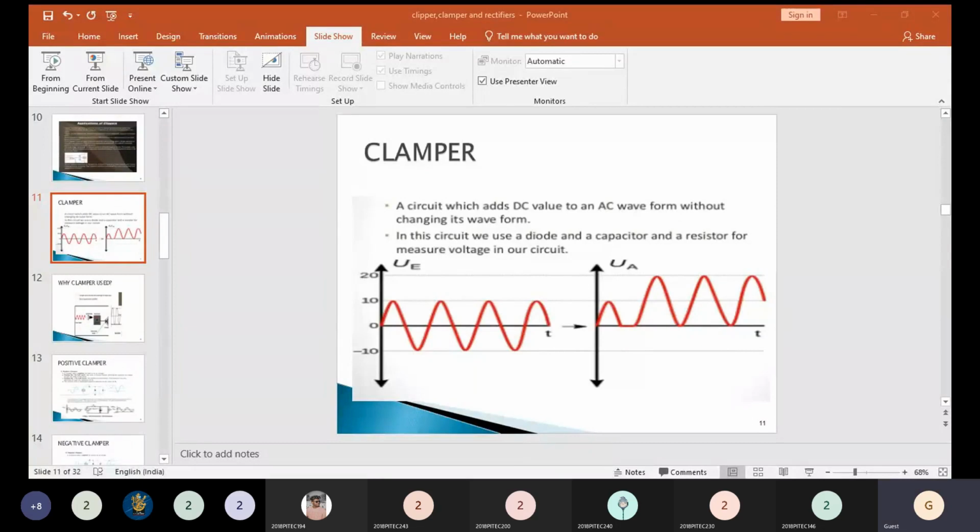Okay, so the next is center tap. The same full wave rectifier, we are using with the concept of a center tapped transformer. Instead of using a normal step up transformer, we are using a center tapped step up transformer. So what is the main drawback of the center tapped step up transformer in implementation? The main drawback is that the circuit will be a bulky one. So cost wise, obviously a high cost. So implementation is also very difficult.